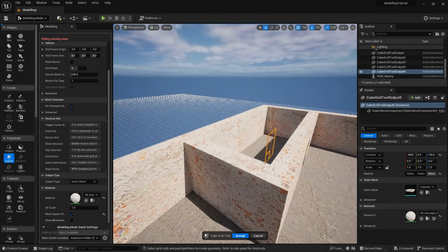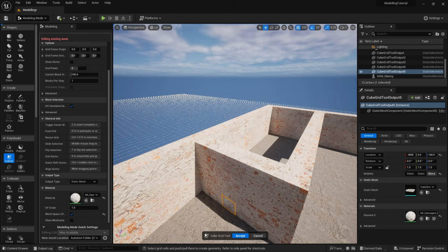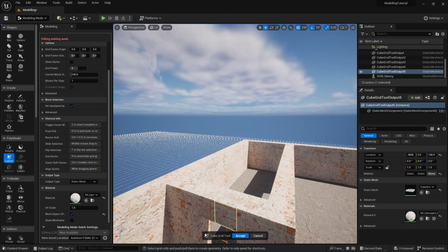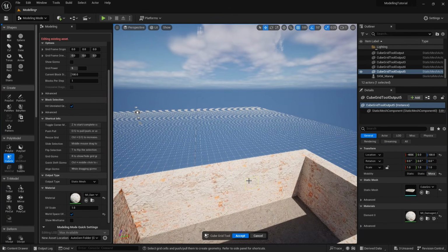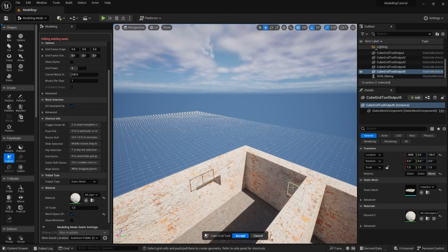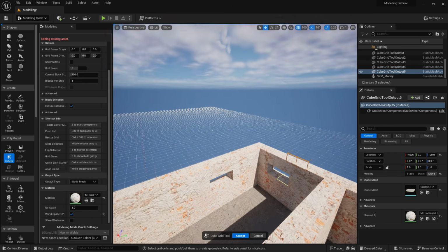And let's put another one over on this side. So again, 3 meter by 2 meter, select, Control key down and then drag backwards. And now let's also create a couple of windows in here. So I'm going to just create a 2 meter window using Control to pull it back, and over here similar thing, and Control and pull it back.